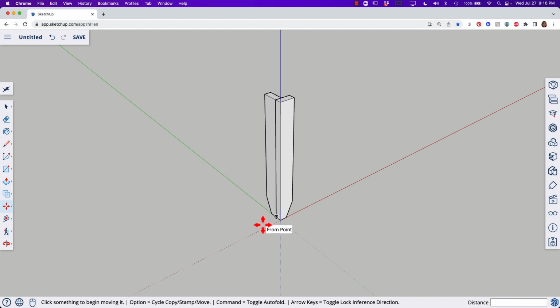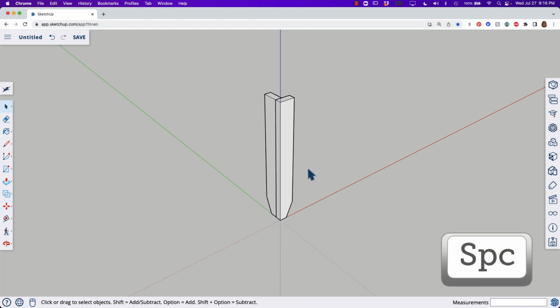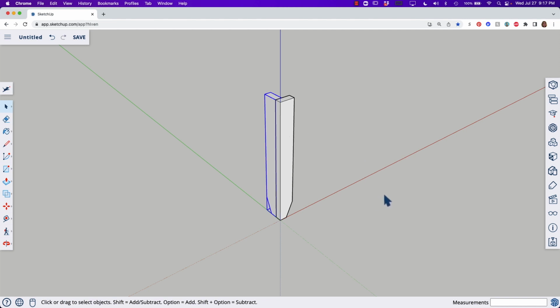However, they're still individuals. Let's press the space bar, click on one, click on the other, and you can see that there are two different legs there. We'd like to combine those into another component called leg unit. Click over to the side, though, to deselect, and I'll show you another trick. While we're here, let's talk about selecting without using the Shift key.